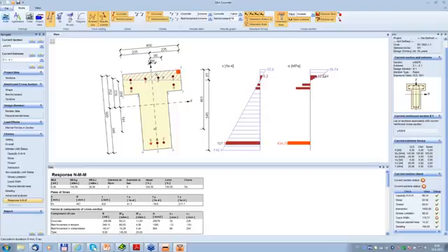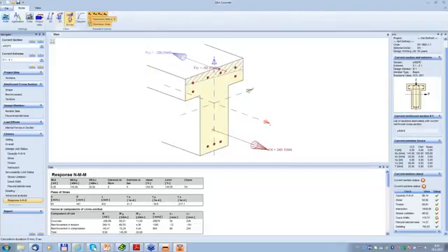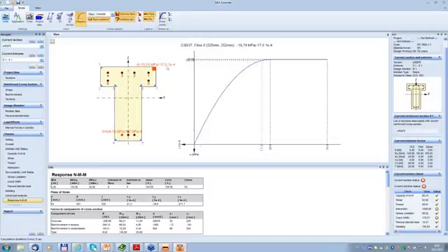You can see probably the parabola here in concrete in compression. You can see the neutral axis. Here these crosses are the positions of resultant forces. This is the most tensioned reinforcement bar, and this is the most compressed concrete fiber. You can switch also to 3D or 3D forces, where the resultants are, or the diagram, and to observe which fiber is loaded in which way.